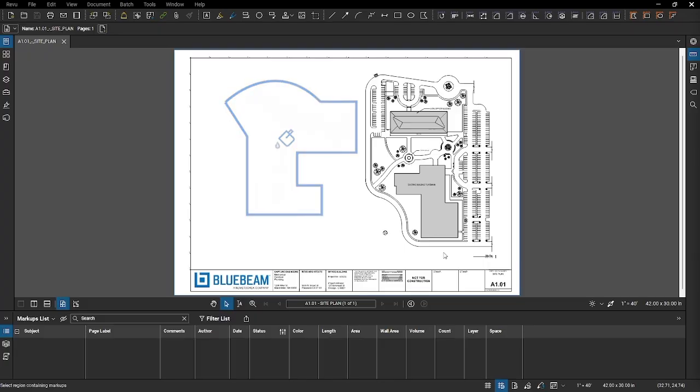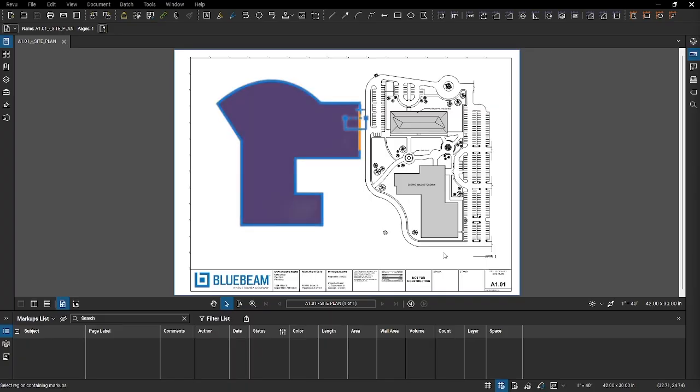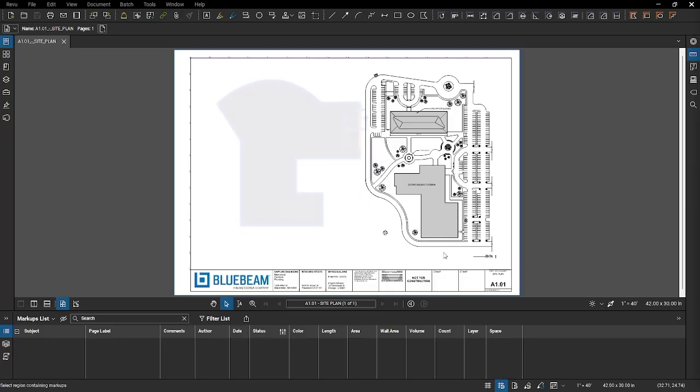Selections are made using the Fill tool, which pours a selection inside of any enclosed shape on the drawing. A boundary tool connects open line work to the drawing, creating a barrier for the fill selection for shapes that are not closed. Once the selection has been made, the selection can be used immediately to create a space, area measurement, poly length, perimeter, volume measurement, markup, or any number of these at once.